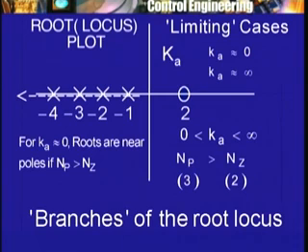We will be looking at some more rules of the root locus method, but in order to emphasize the power of the root locus method, let me give you the solution that the Evans root locus approach is finally able to give you. I have this pole-zero diagram. I am going to start at these three poles, I am going to end at these two zeros, and one branch is going to end towards the negative real axis. Alright, now what is going to happen in between?